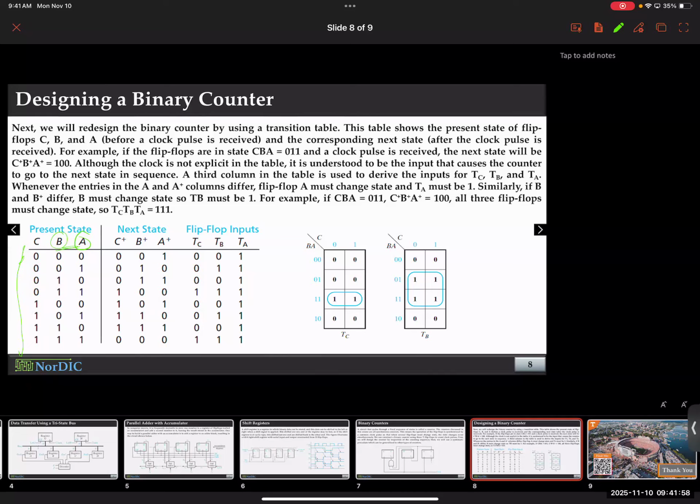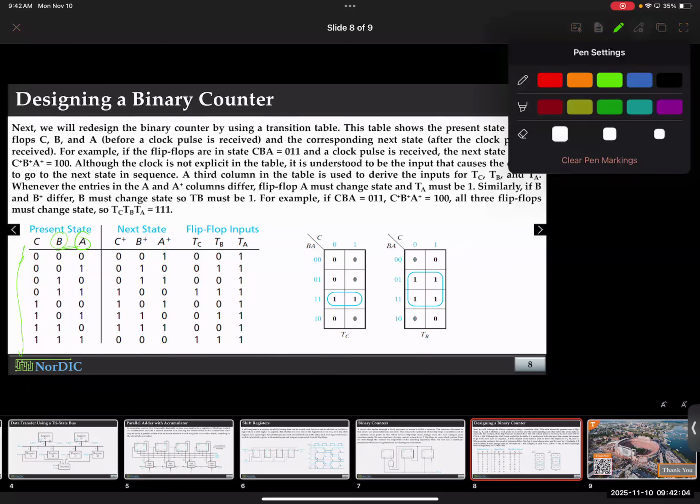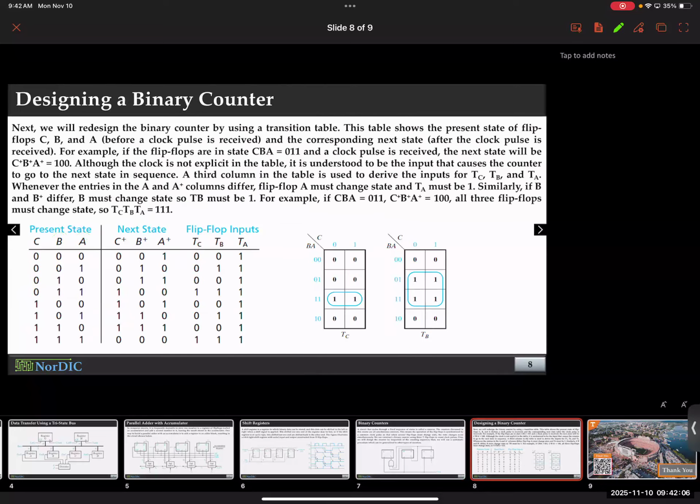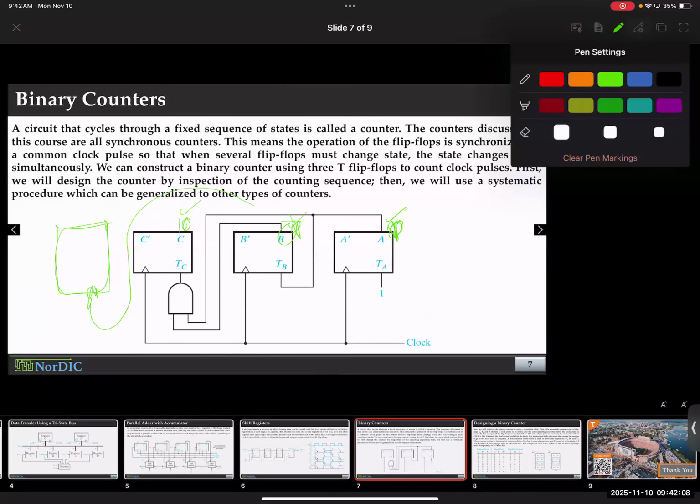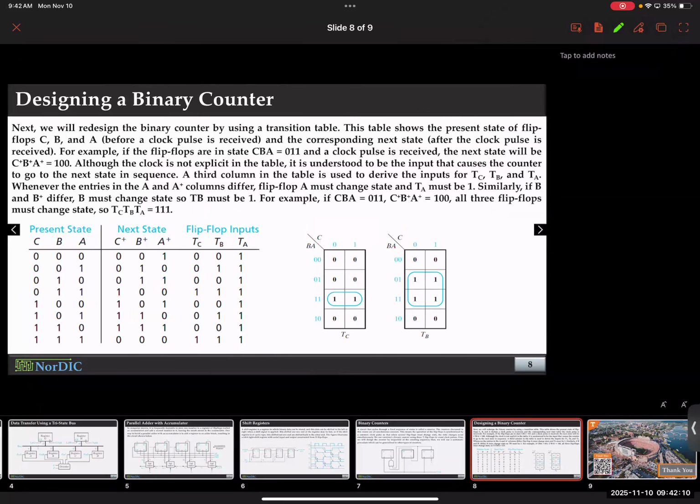But if I didn't know it, it would be impossible for me to discover the pattern within my class period, right? So there has to be a better way. What is the better way? The last slide will show you the actual systematic way to do so. This is the last slide for this lecture, all right? This is basically our well-known K-map. We could use our K-map to design these flip-flop circuits as well. Okay, let me show you how.